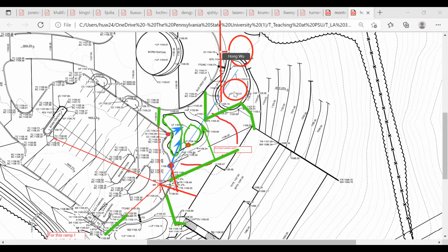So this one would be at a higher elevation, and that one would be at a lower elevation just because of the trench drain. Right now, because the 5 wraps around like this, contours here definitely would not be the same. You have 5 over here as well, so you actually have a natural berm. You're going down and then going up, so you likely won't have to have a lot on the other side because 05 is naturally on the other side.